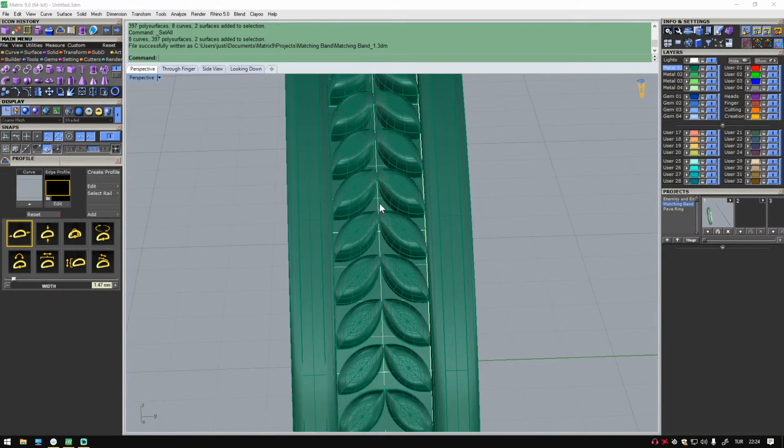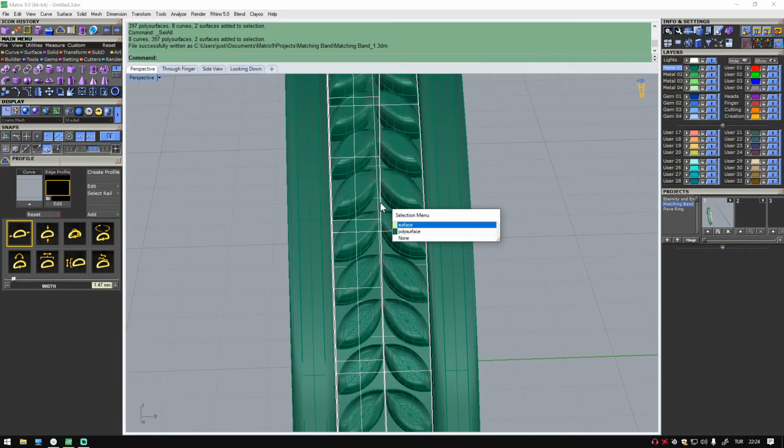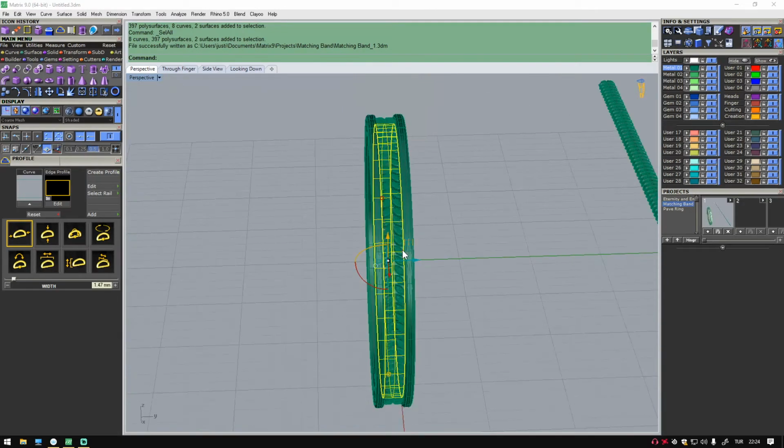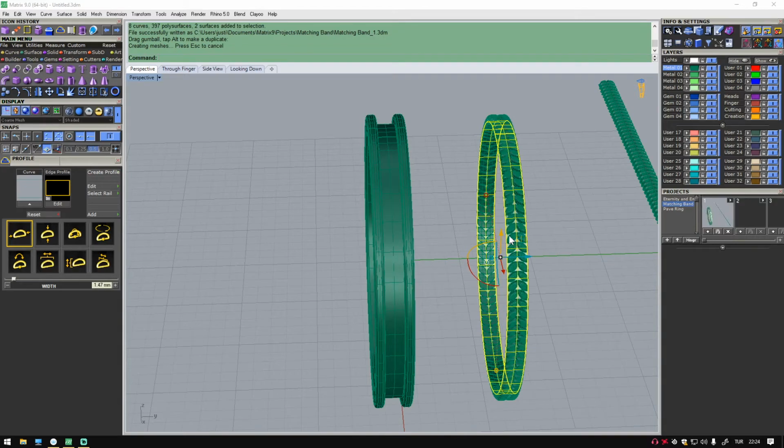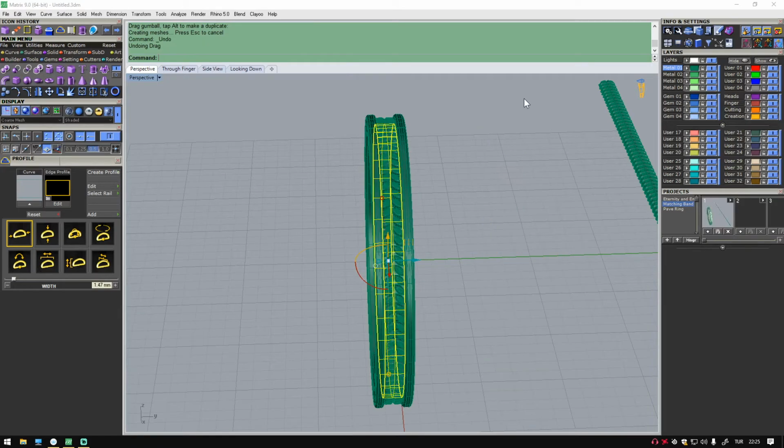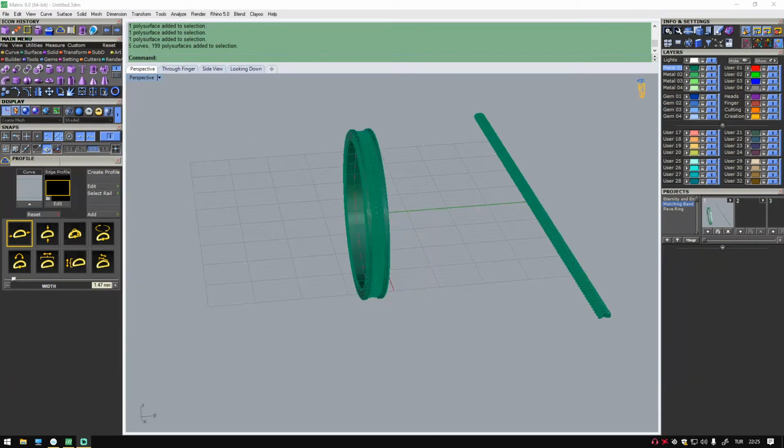Now I can delete what's extra, which is the surface that we extracted. It's extra, but if I move it, because it's working with Rhino's history command, the pieces are moving as well, so you also need to be careful about that one. I'm going back with Ctrl Z and delete it before moving. Okay,